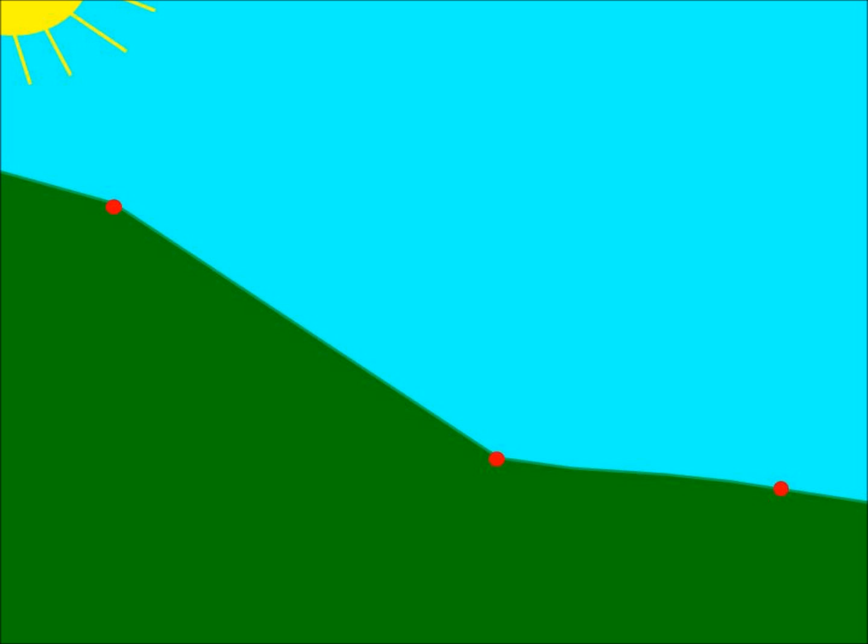Also, you need to be aware of how your data points are going to represent the terrain. You'll basically be interpolating the terrain between data points, so make sure you get shots where the slope changes. These points are called grade breaks. If you don't get shots at these locations, you will interpolate incorrectly and get an inaccurate representation of the terrain.